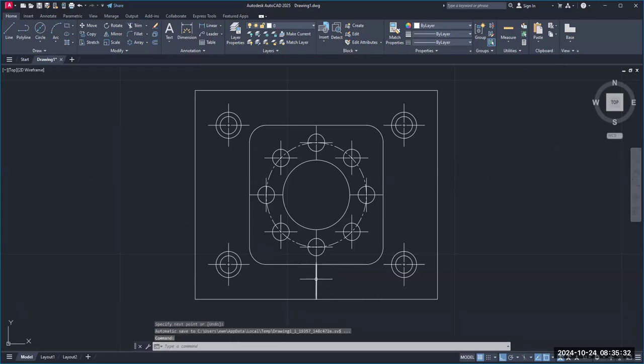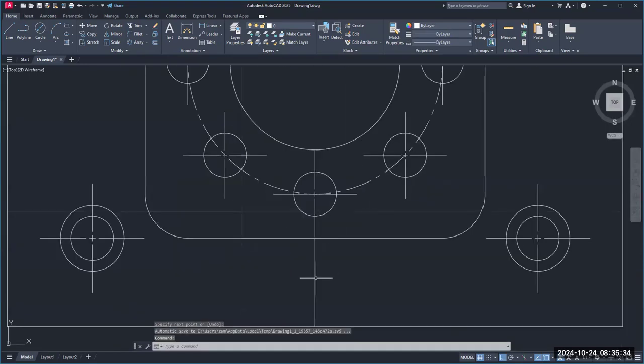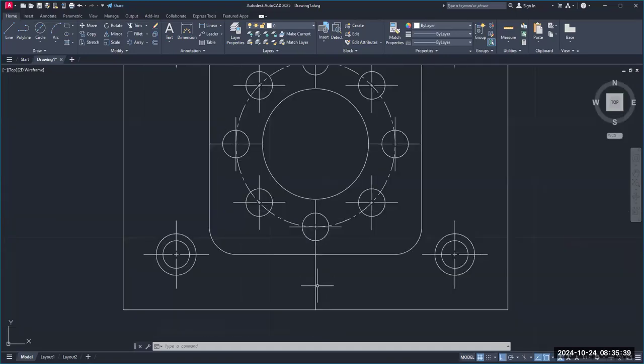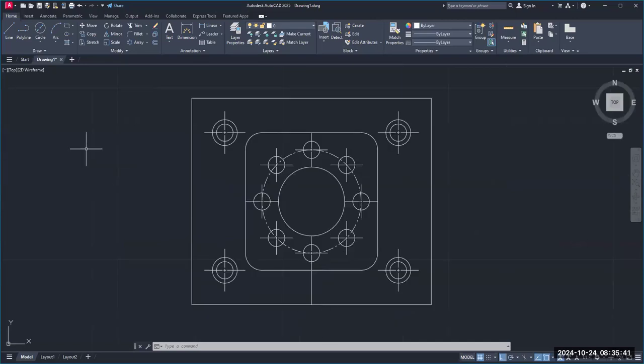The reason I drew a line here is because I'm going to draw 2 concentric circles right at this location. So I'm going to go to circle, center diameter, move your cursor over to this line. A triangle will appear. That's the midpoint of that line. And click on it, and we're going to drag this out.